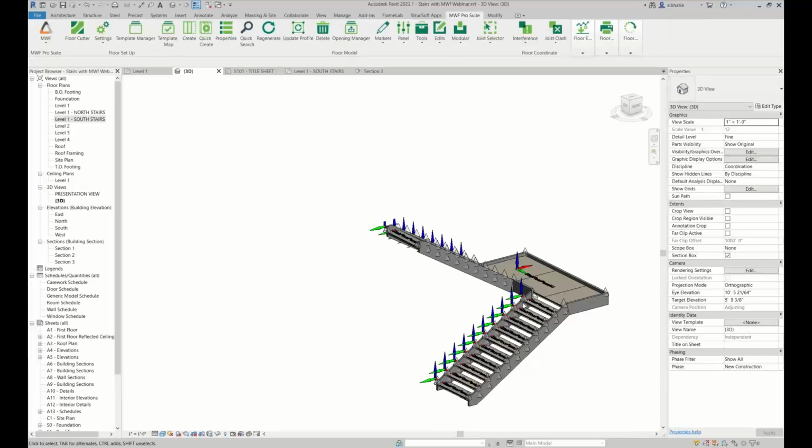And then just make sure you didn't have any joists placed at all, so the spacing for your joist would be ridiculously high. So you'd only have the start and the end joists created and then your end tracks created. So yeah, that would be the way I would do it if you want to really frame it. But I would create a sloped floor in that location and then do it that way.